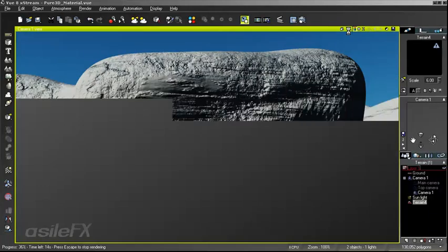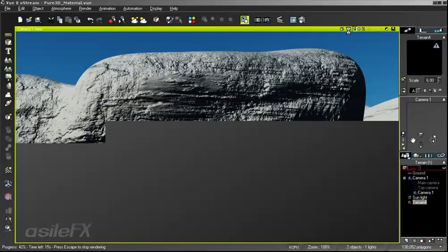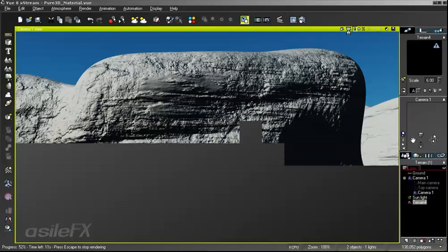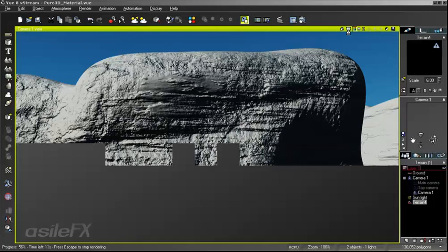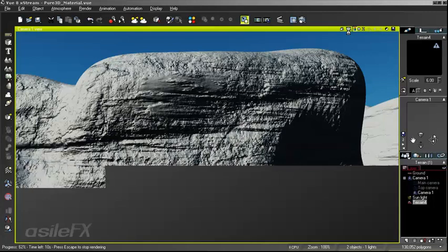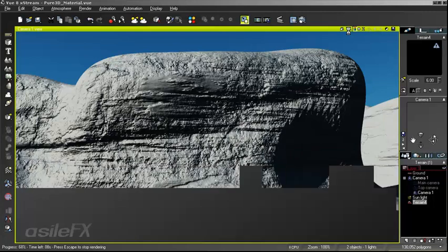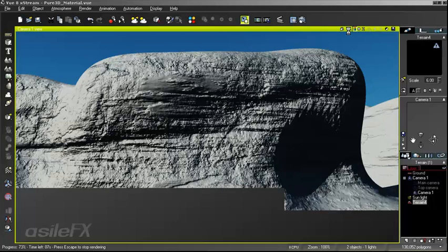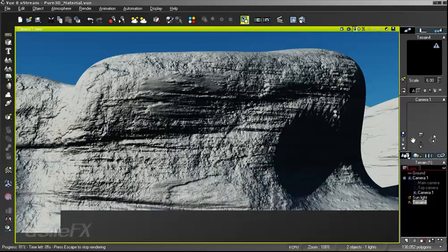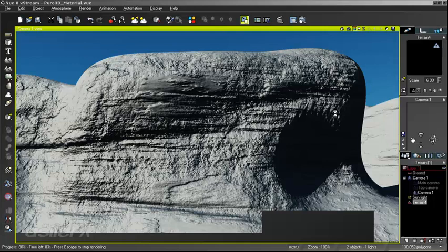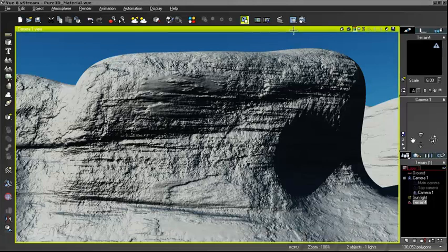If you take a look, there's a lot of very fine grit within the material. The roughness setting is possibly too intense. So we can go into the fractals, reduce the roughness settings, and we can also get a good idea of where we're going to run into problems later. Anything showing up now in the form of ray tracing errors in a render are going to be problematic areas later, so something to pay attention to.